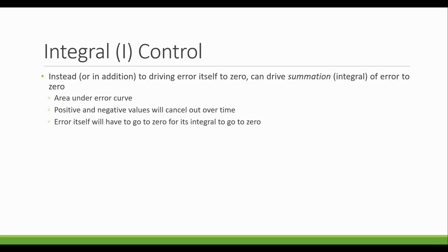We saw previously, using a proportional controller, that the closed loop system and the open loop system, or the plant, had the same order. They were both first order systems for this case. That's not going to be the case when we put in an integral controller. It's actually going to change the order of our closed loop system, which can be a good thing because it gives us some options of how we want to design the controller to get a desired response. And we'll go through that for, again, this same plant.